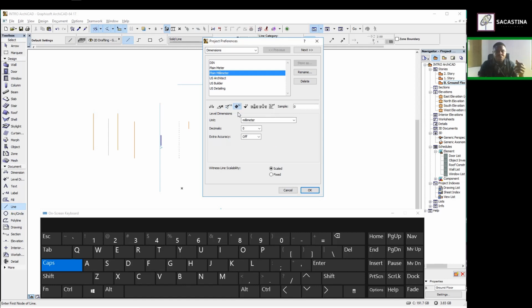Now we have story levels. If you are working on a building, you have a story level, you change it to what you want. You want your elevation level, whatever it is you want. Everything is just there. Just like you have your area calculation in ArchiCAD, you can actually calculate the area of a certain work so easily, quicker and faster. It has set its own default already here. You understand? But for that of area, I don't use millimeter. What I use is meters square.